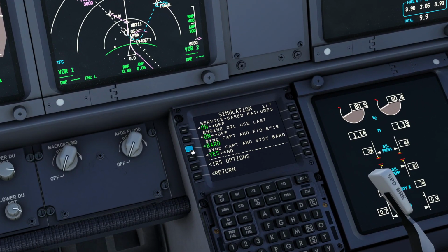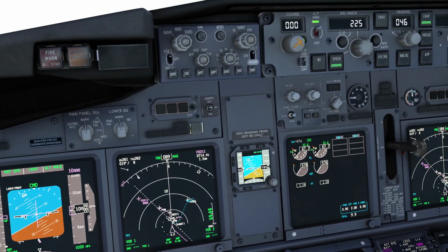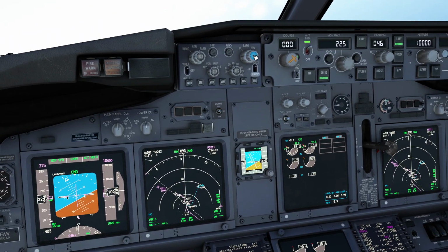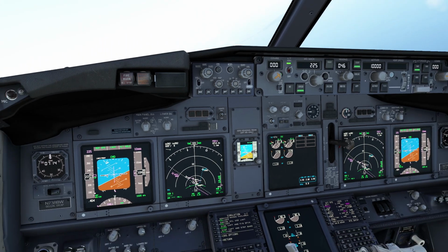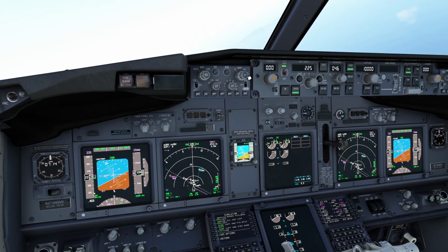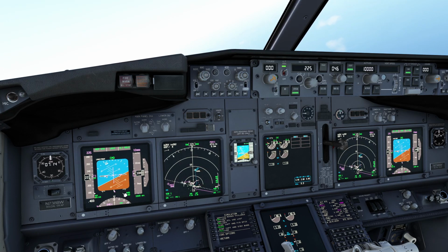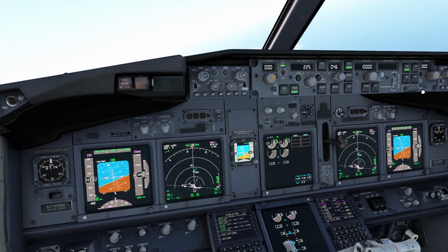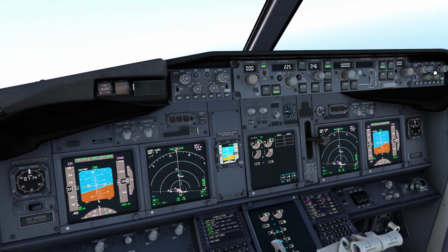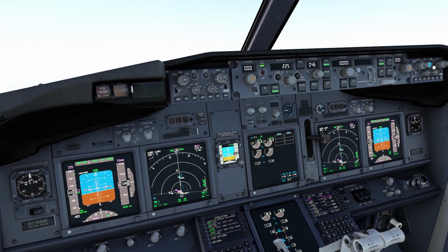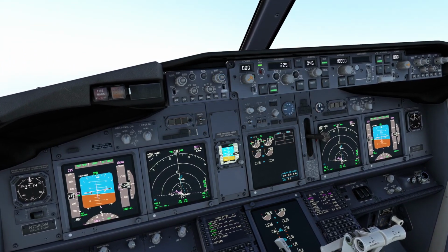The next option is only the BARO, so it's going to be only your altimeter setting, not the minimums. So if I have BARO and I set it to standard, now you see both sides change to standard, back to 1020, but the minimums I just show on the left side and on the right side it's not there. And vice versa. If you only keep BARO, so only the right button will be working.